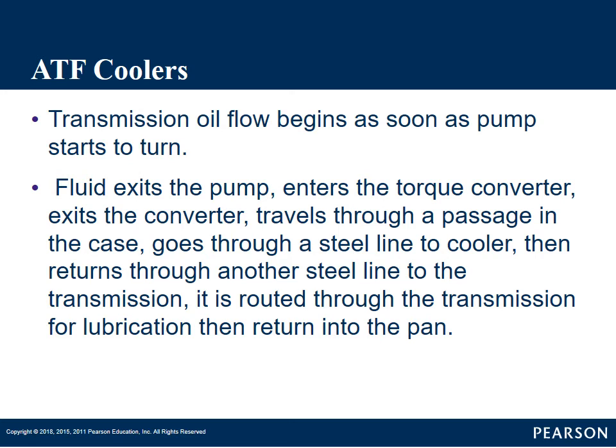So you can see why it's important that this is not too hot. Fluid breaks down when it gets hot. Fluid viscosity breaks down. You don't get proper lubrication. You damage internal transmission components. Okay. From there, it gets returned back to the pan. If it doesn't have a pan, just the sump of the transmission.